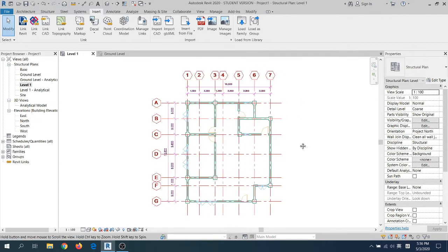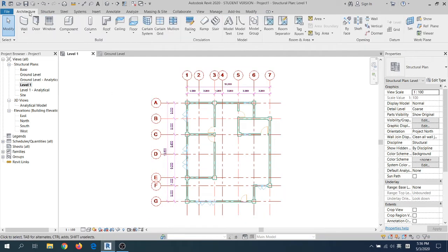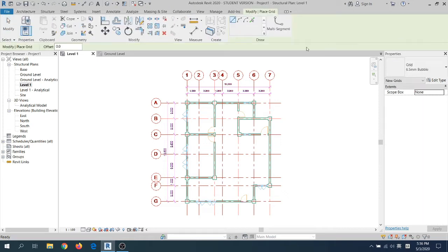In order to draw my own grid line, I use it as a reference, or actually a base for me to draw it correctly instead of redrawing it and doing a big line one by one. Just click grid line and then I can draw it accordingly based on the reference line from my architecture file. Quickly, I just follow the line based on the CAD drawing.